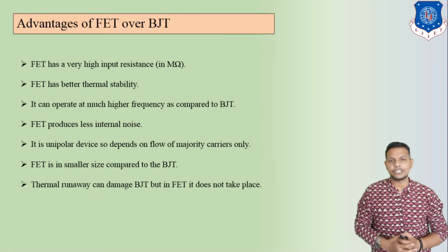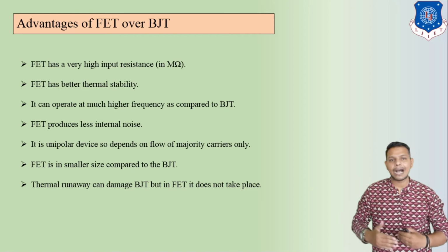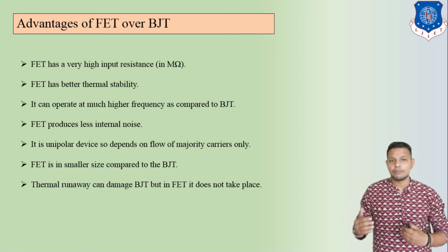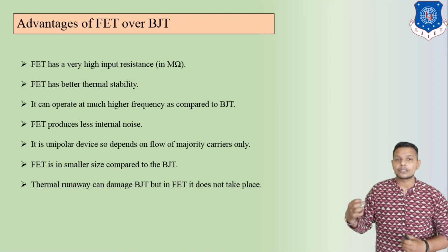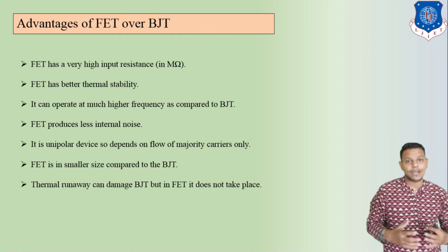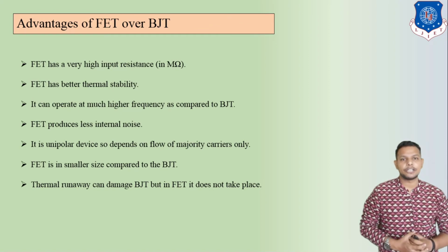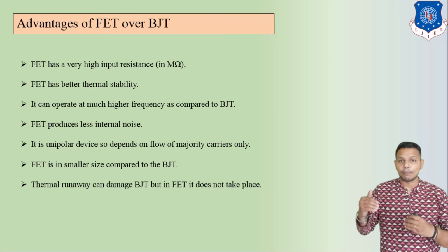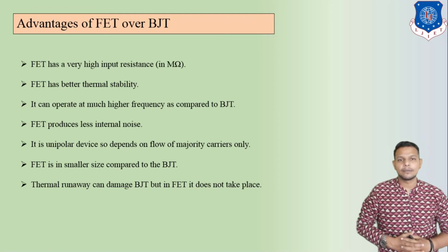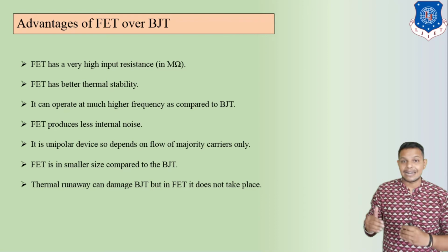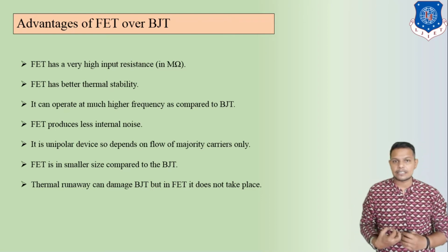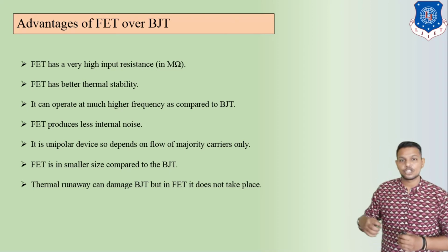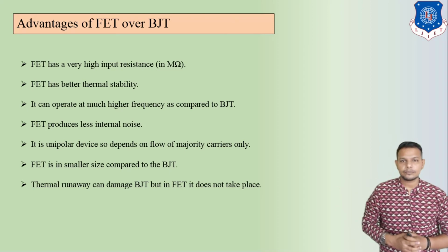Here are the advantages of FET over BJT. FET has a very high input resistance, which is in mega ohms. It might be 100 mega ohm. FET has better thermal stability, so that's why we are using it over the BJT. It can operate at a much higher frequency as compared to the BJT. It produces lesser noise, lesser internal noise, we can say precisely, than that generated in BJT.